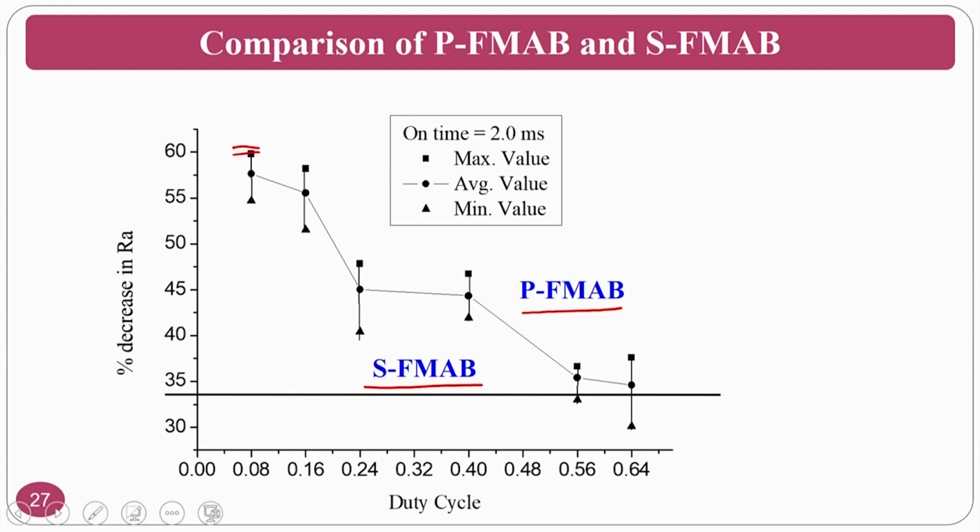Okay. So, why is it achieving this? Because the chain is collapsing, and whenever it collapses, the abrasive particles change. First point, abrasive particles may reorient and the chain in the second formation may be a better chain. Many possibilities are there in the pulsating type of flexible magnetic abrasive brush.